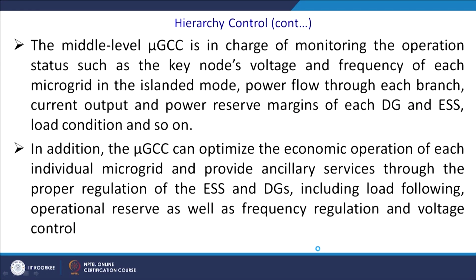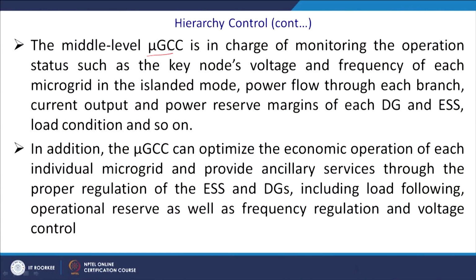So, based on these discussions, what we can say is that the middle level microgrid controller is in charge of the monitoring and operation of substations, key to the node voltage and frequency of each microgrid in the islanding mode, power flow through each branch, the current output, the power reserve margin of each DG, and the coordination between the load and so on.